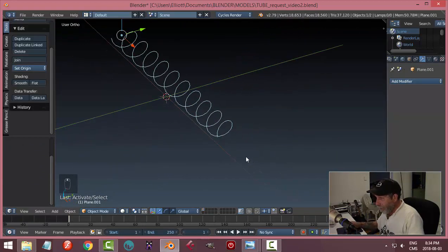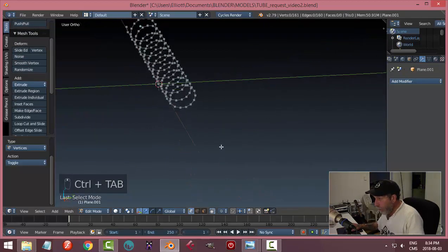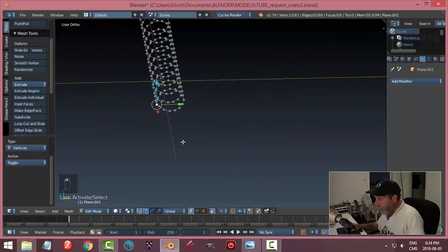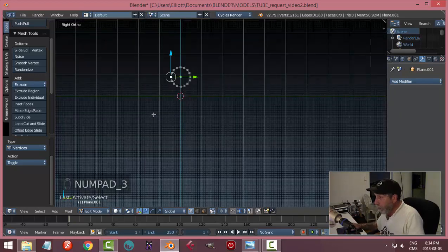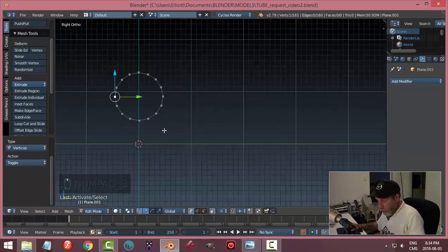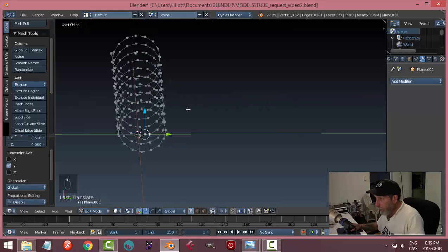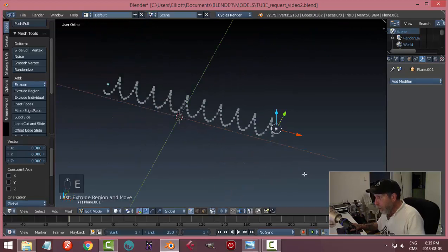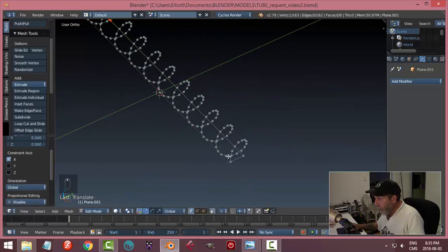Well, we could do it anytime, but now I'll go into this in edit mode, and in vertex, here's my plan. This vertex at the end, I'm going to send an edge going down through the middle. So let's go to the end and see it, and I think I'll just go E and come straight back into the middle. Maybe even a little bit over to the side. All right, and then I'm going to start E, and I'll just kind of send this back through. We'll work on that end in a minute. Let's come back to here.